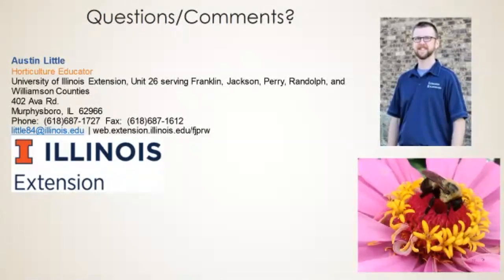And actually, in more northern climates, permeable pavement systems are going to have a longer survivability than conventional paving systems because they withstand the shrinking and thawing, contracting and expanding a lot better than conventional pavers, because they've got a lot more space to move. They've got more airspace, and water moves out of them faster too, so there's less freezing and thawing that happens. But as far as the snow removal, it's really just removing snow. It's going to be the same, only ice and snow should in theory melt off of them faster than other kinds of impervious pavements.